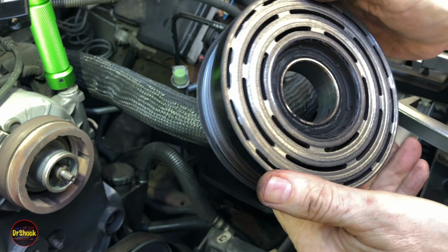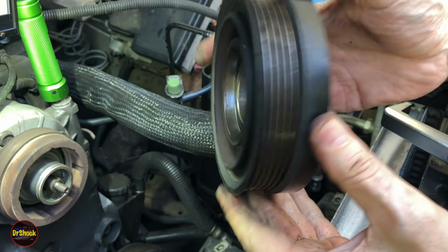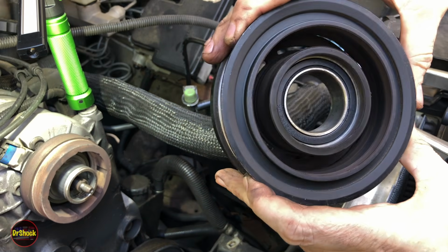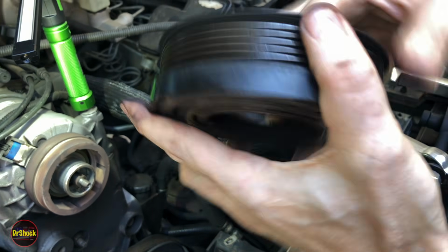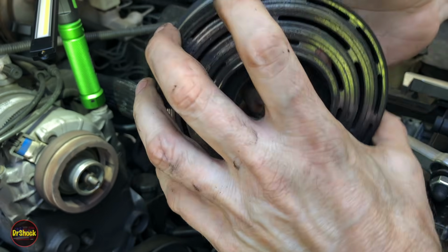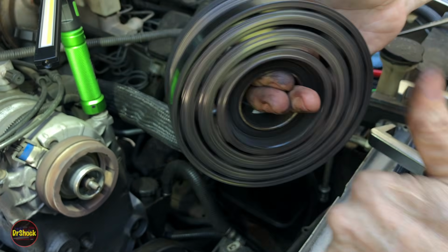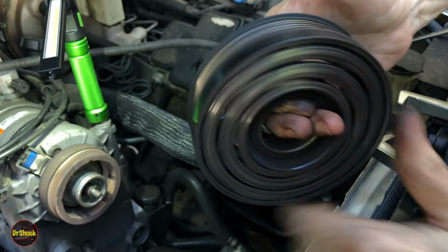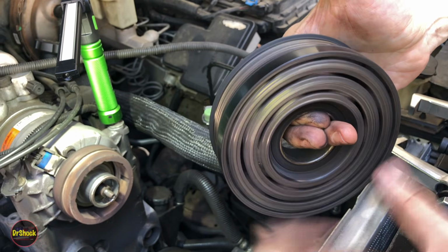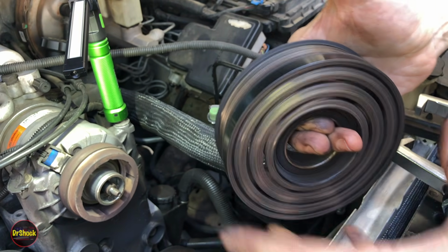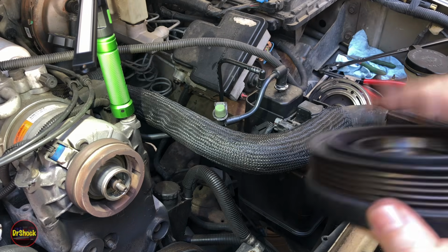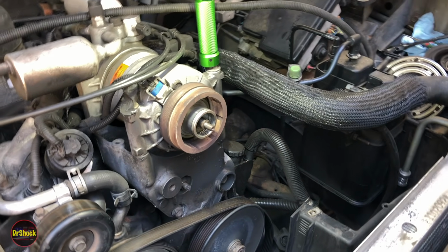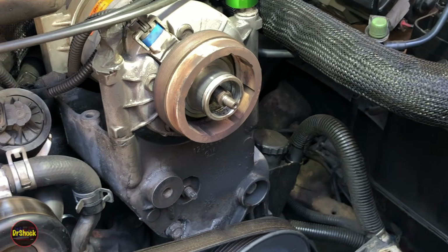So this part of the assembly is all solid machined with the pulley, and then the bearing is pressed inside. So this is often why you'd be wanting to do this kind of thing, is to replace this bearing. This particular one is smooth, no sounds, no vibrations. If we found that it wasn't, we'd need to replace that too, but we're good. All right, so now that piece is out. And now's our prize. We're after this guy.